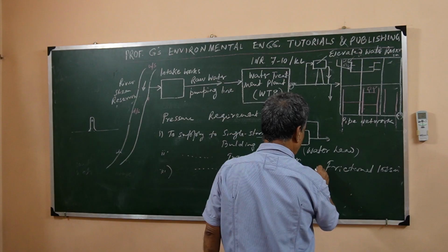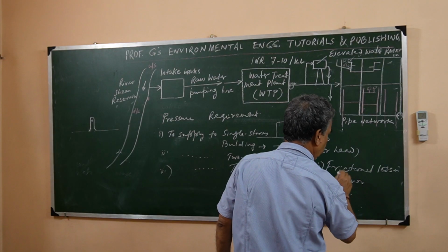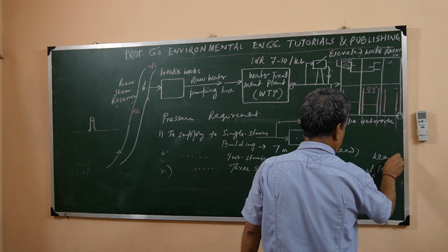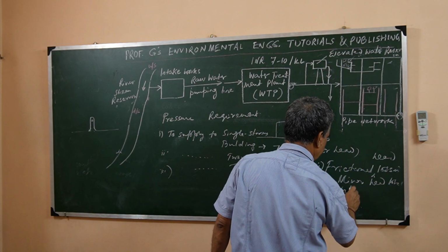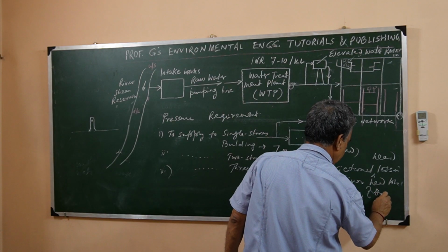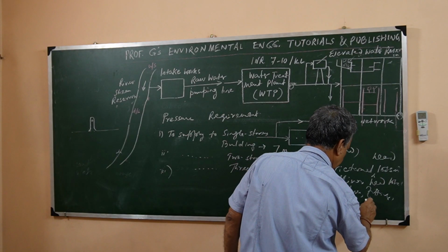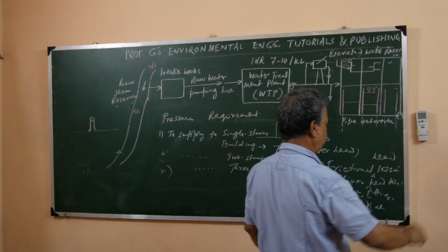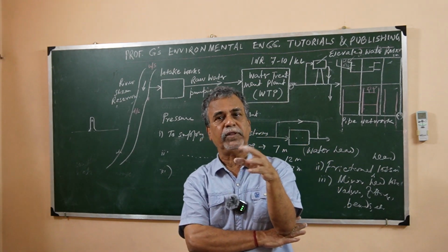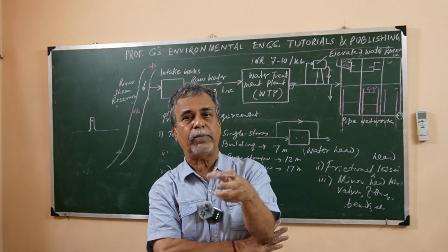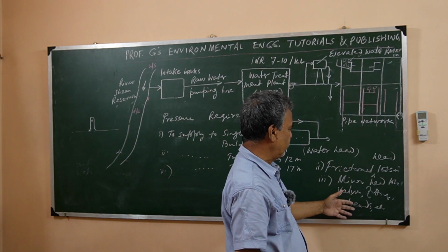Then also this is minor losses, I mean head losses, of course. This is minor head losses due to valves, fittings, vanes, etc. in the pipeline. Many appurtenances or ancillary components may be there which are an integral part of the water supply system. In that case, accordingly, the losses have to be calculated.